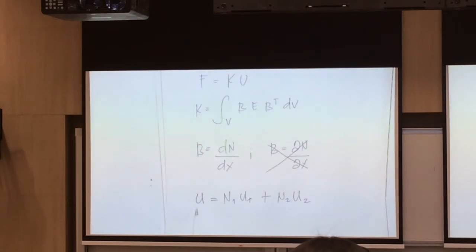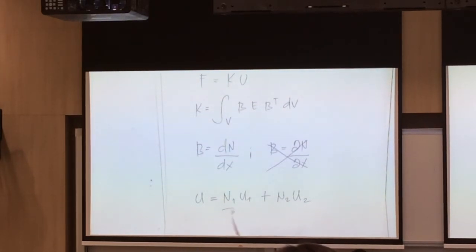What we did was we just took a linear displacement function. We determined your shape functions, which are basically linear. Very simple. Shape function meaning N is equal to 1 at the node of interest and 0 at other nodes. Example, N1 at 1 is 1, N1 at 2 is equal to 0. So that's basically the definition of your shape function.